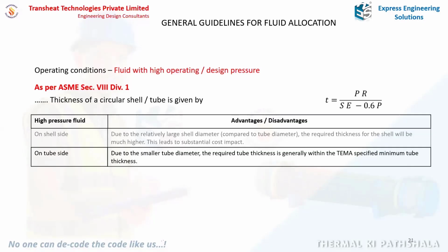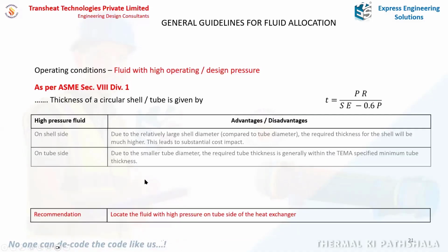So you are not increasing any thickness of the tubes beyond what is recommended by the design codes. So there's no cost impact because of this generally. So the recommendation would be to place the high design pressure fluid on the tube side so that you save on the overall cost of the unit.